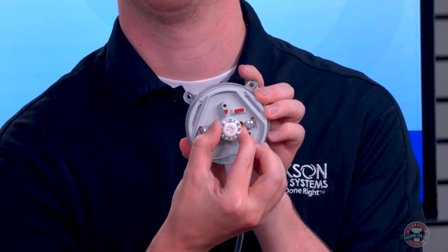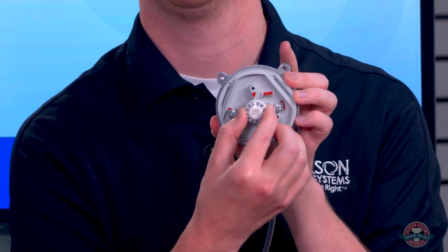And this is the dial where you say, hey, what static pressure is too high, basically. We ship it at 0.35 inches of water column, and you can adjust it to your heart's desire. The nice thing is it's fully calibrated too. So when you get it from us, if you set it at 0.35, it's going to be right on 0.35, so you don't have to get out any test equipment. Just set it. And the cool thing is you can set it on the fly too. You can actually sit there and adjust it and watch it work. If it's close to the ESP panel, you can crank that thing all the way down, and you'll see the ESP LED on the panel light up and say, hey, the static's too high now.